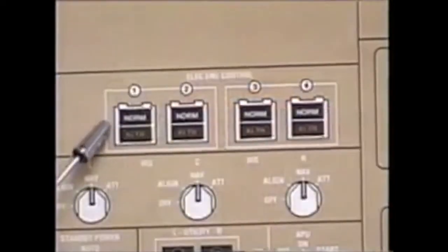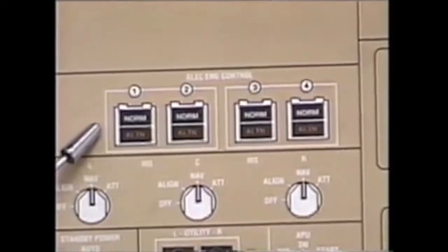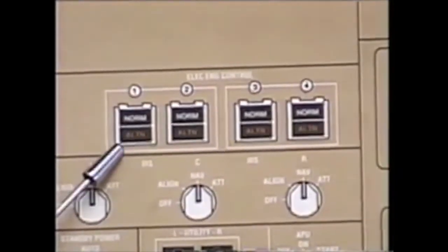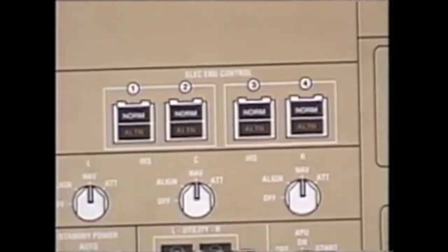Our review today will start in the upper left-hand corner of the overhead panel with our electronic engine controls. Each EEC has two modes of operation. There's a normal and an alternate mode. With the EEC in normal, EPRs are controlling parameter for setting thrust. The normal mode will provide overboost and overspeed protection for both the N1 and N2 compressors. In the alternate mode, N1 is the controlling parameter. There is no overboost protection, however you do retain the overspeed for both the N1 and N2.